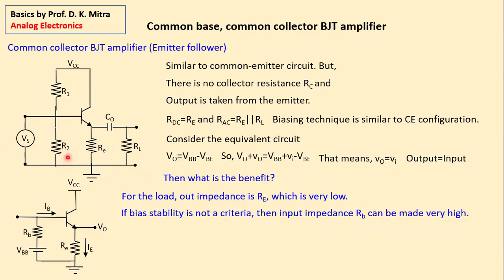That is why we always want for a voltage performance, input impedance should be very high, output impedance should be very low. So this special configuration, not common emitter, but emitter follower, provides this special facility. It provides an excellent isolation between two stages. Later on, if you really go into analog circuit design, very often you have to create an isolation stage.